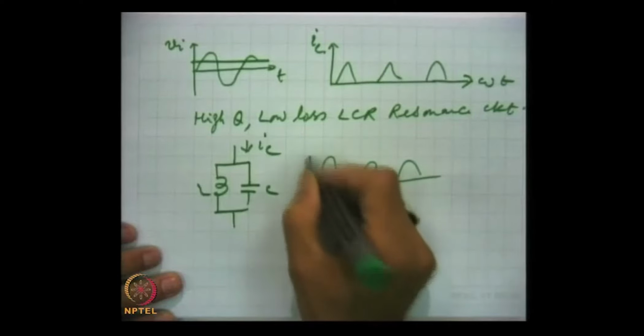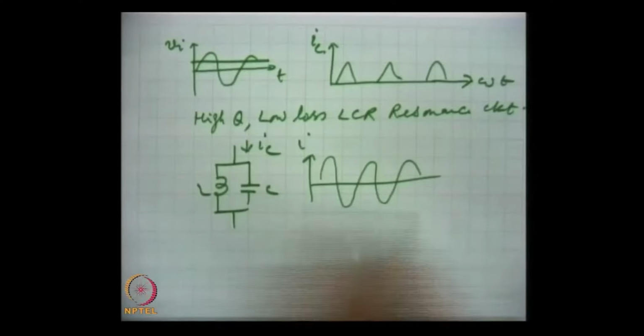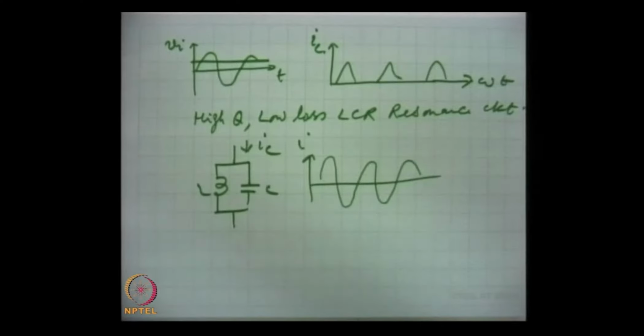The output available is this. So, why class C amplifier? What is the advantage? Efficiency. The efficiency of class C amplifiers is above 95%. For class A amplifier 25%, class B amplifiers more than 75%, and for class C amplifiers this is in excess of 95%. So, this is a big consideration, but there is a limitation.